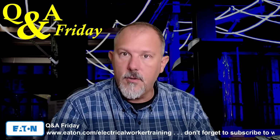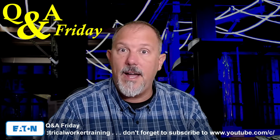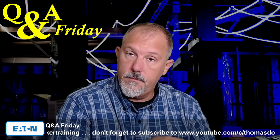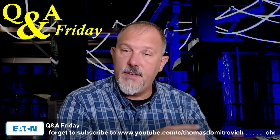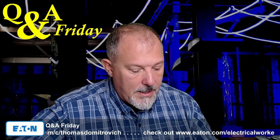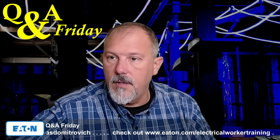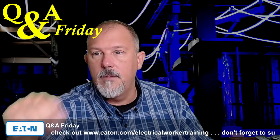If you don't have a receptacle in there and you hardwired to it, then you have to provide GFCI protection for that outlet, which will have to be upstream, either in a receptacle or a blank face device that is providing that protection, like a wiring device or a circuit breaker. And I agree, we use that term in multiple locations. There are other situations where it says for, like in bodies of water.